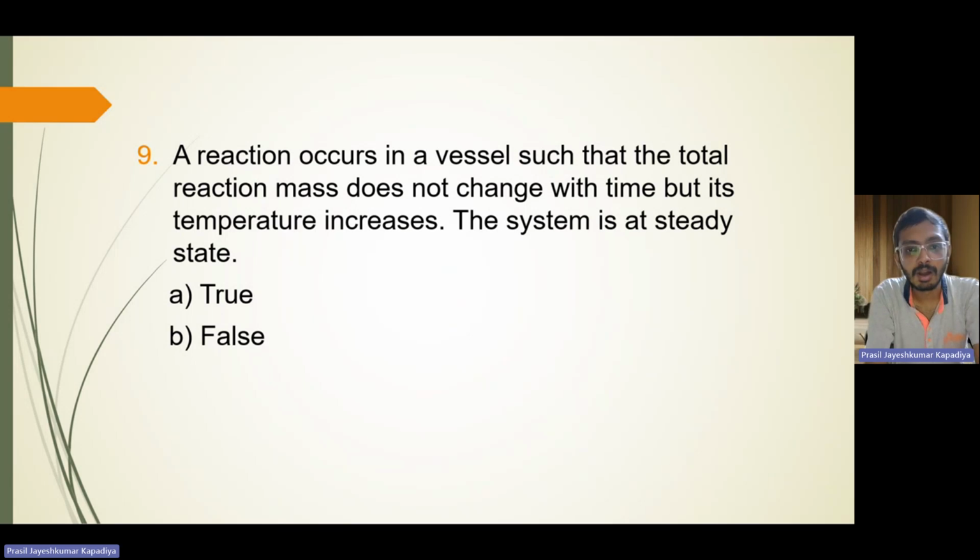The question is, a reaction occurs in a vessel such that the total reaction mass does not change with time, but its temperature increases. The system is at steady state. Is this true or false? This is absolutely false. So what is the definition of steady state? When the system is at steady state, all properties with respect to time do not change. All properties like temperature, pressure, mass, nothing should change with time.